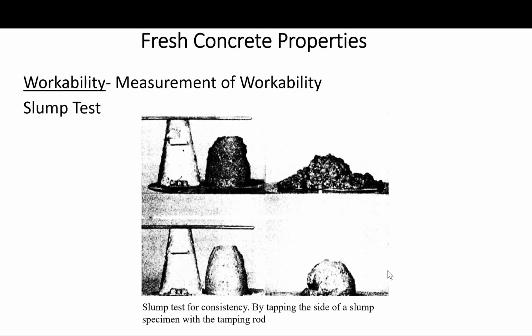Okay, so more about slump. There are a number of difficulties associated with the slump test. The test is completely empirical, and as I said, is not related to our earlier definition of workability, which involved the measure of the amount of energy required to compact concrete. With different aggregates or mix proportions, the same slump can be measured for different concrete consistencies.